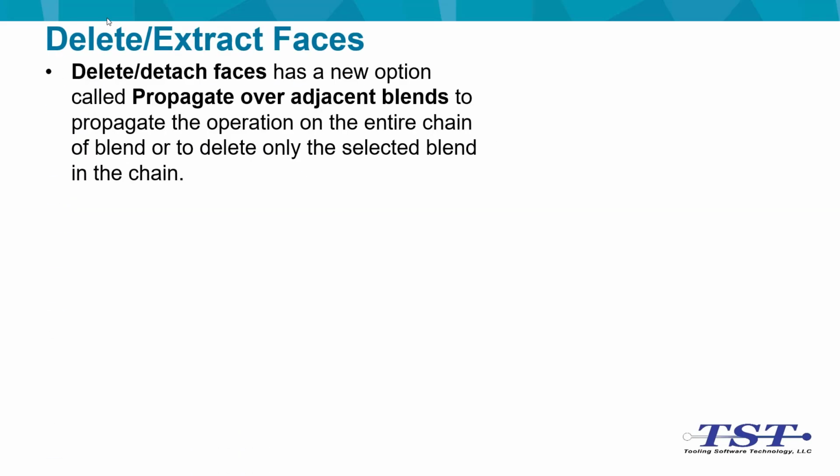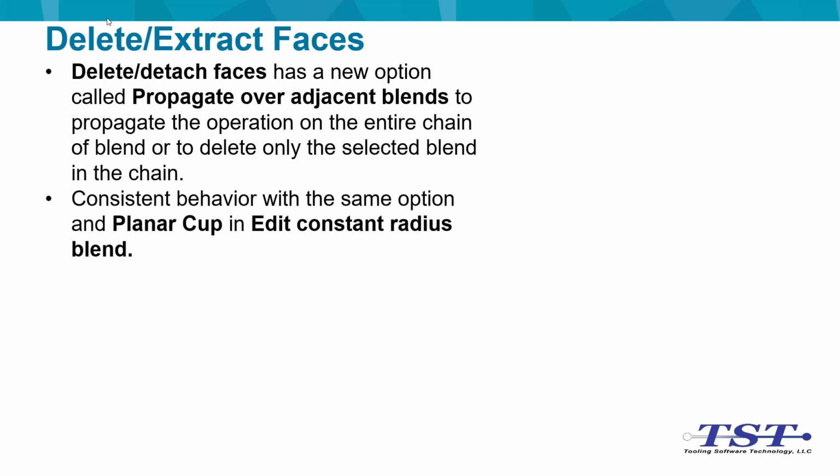Within delete and detach faces, there's a new option called propagate over tangent or over adjacent blends. The propagate option allows you to entirely chain the blend or delete any selected blends. So it's a nice command for being able to pick an individual blend and delete and heal it, and it cleanly deletes and heals it. I can tell you, doing some of our training examples, this has vastly improved the quality of how we would be approaching this compared to previous versions.